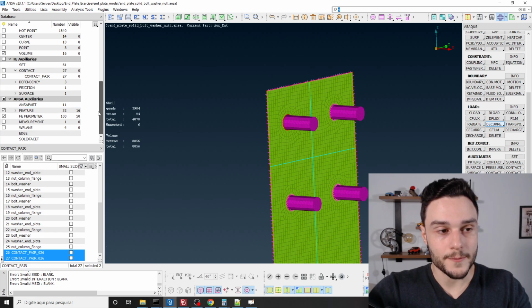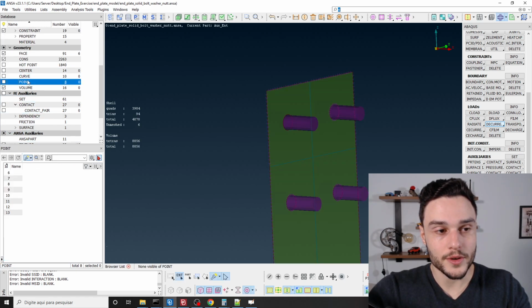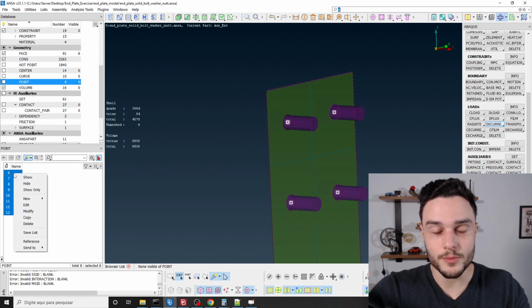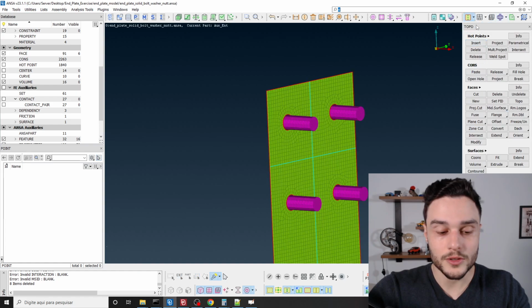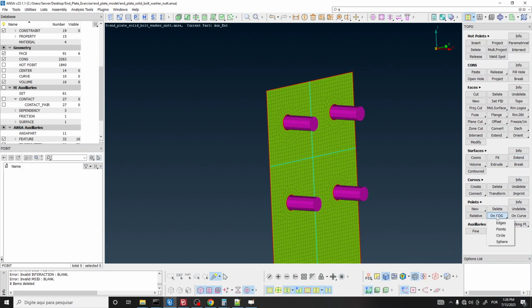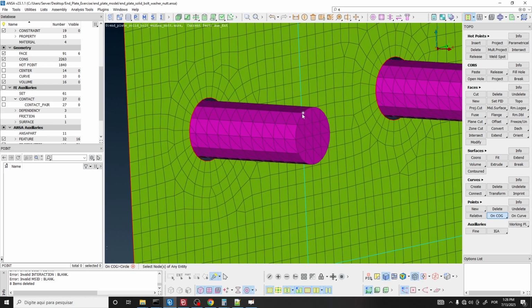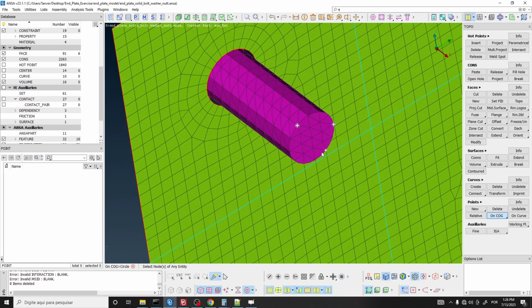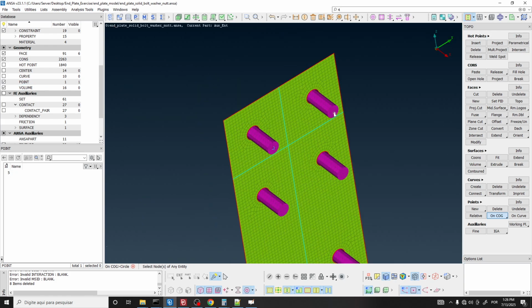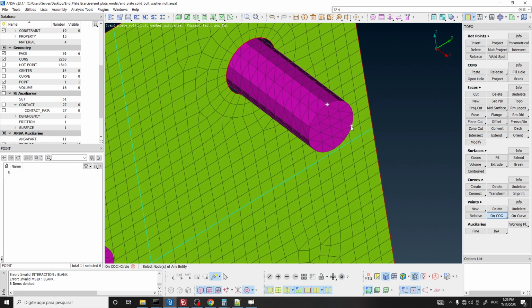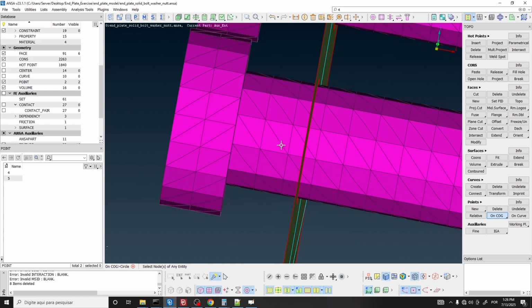In the database, double click on points, we have 8 points. I'm going to delete all these points, delete, so that we don't get confused. I'm going to the classic topo module, and then here points on COG, circle, and then the first point is going to be here. Select 3 nodes from this circle, middle mouse button, activate point visualization in the database, and here we have the first point. Do the same thing here. There we have it. Now the second point is going to be here.